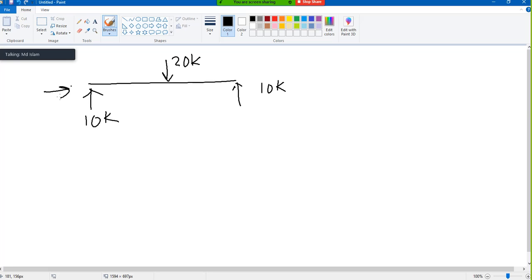For this problem, there is no normal force. In fact, in most cases in beams there is no normal force, because in civil engineering most of the load is vertical. If there is wind load or earthquake load, which is lateral, then we get some normal force. Otherwise, there is no normal force. It is very rare, and in most exams nobody asks to draw the normal force diagram because it is not so common.